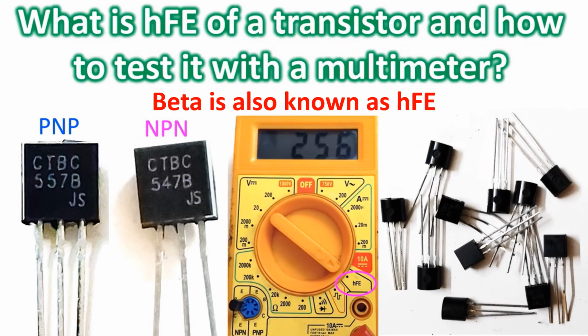We have both NPN and PNP types of silicon transistors. NPN and PNP designations depend on the components of the transistors. N-type material has extra electrons, while P-type has holes, or regions deficient in electrons. The different types are made by adding small amounts of impurities to silicon by a process known as doping.